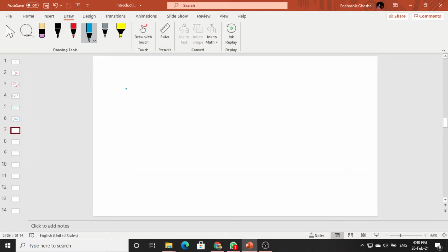Now in a circuit, impedance can consist of both inductive and capacitive reactance. So in that case, we write j of XL minus XC. If XL is greater than XC, we write it as R plus jX.